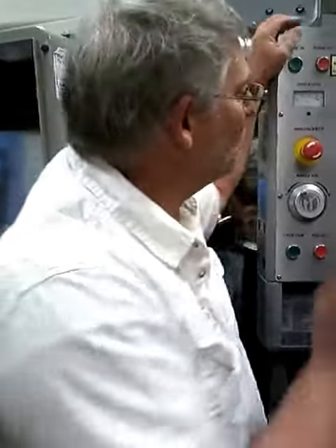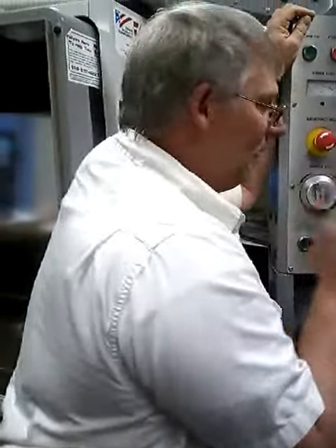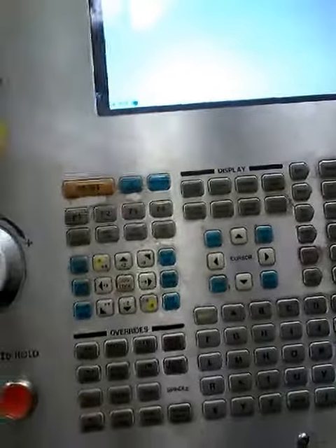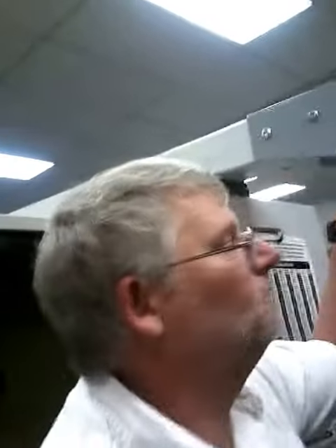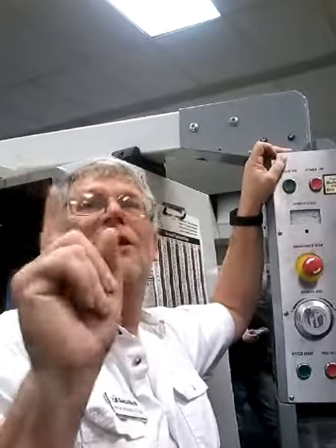What happens, where is this machine going to move if I simply tell it now, X0 Y0, end of block, insert? It's going to go to the active. No, I corrected the original. It's going to go to the home. Huh, is it? No, it's going to go to zero. Why? Because that's where we've told it that zero is.